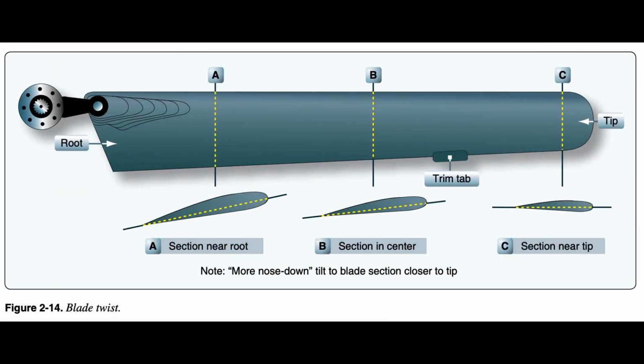Blade twist. Because of lift differential due to differing rotational relative wind values along the blade, the blade should be designed with a twist to alleviate internal blade stress and distribute the lifting force more evenly along the blade. Blade twist provides higher pitch angles at the root where velocity is low and lower pitch angles nearer the tip where velocity is higher. This increases the induced air velocity and blade loading near the inboard section of the blade. Figure 2.14. Rotor blade and hub definitions.